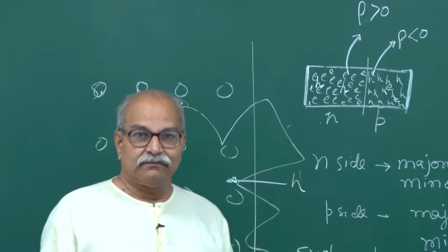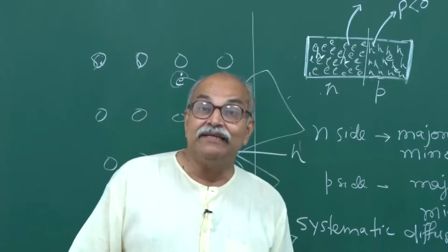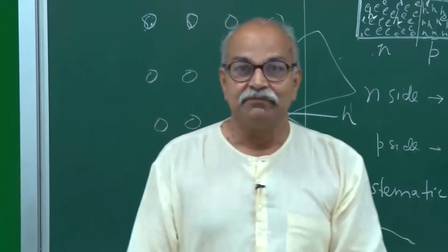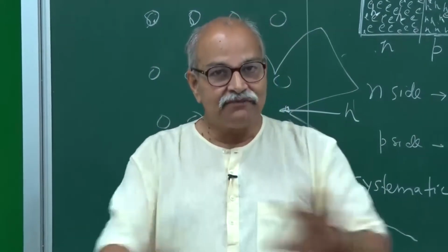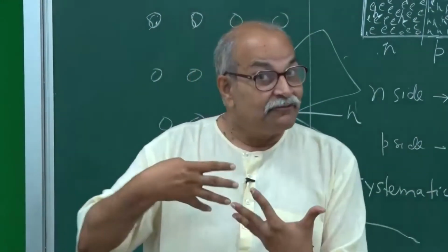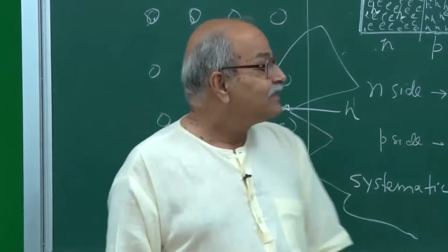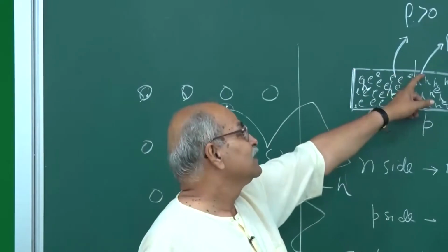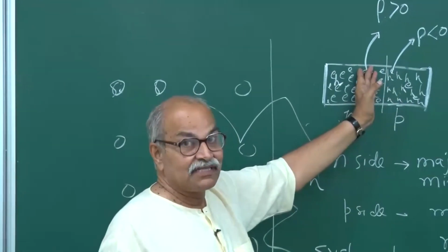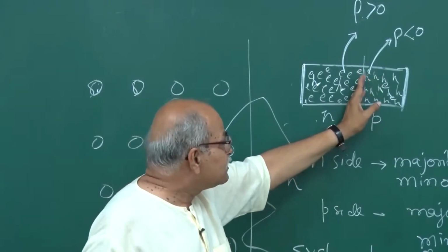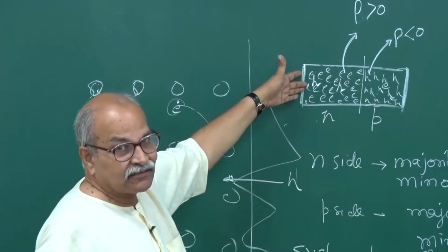So, in an N type or P type semiconductor, if you just have one semiconductor, P type, you do not have charge density, but if you make this p-n junction, then the charge density will appear. You will have positive charge density on one side, negative charge density on the other side. But this thing does not extend up to the end.